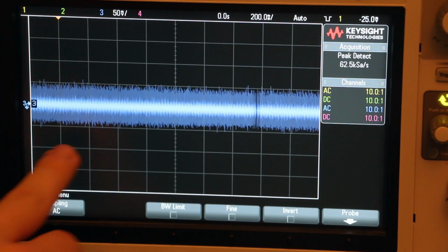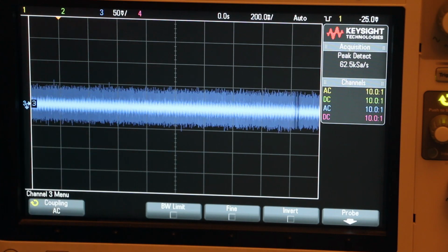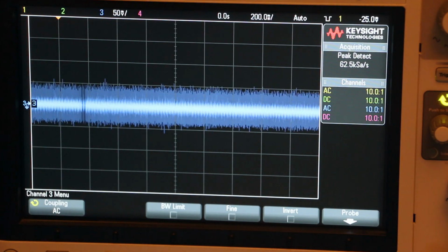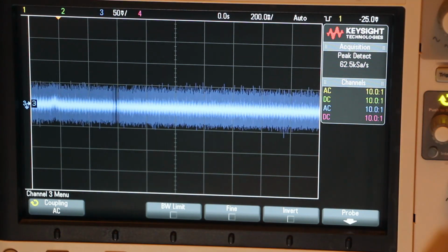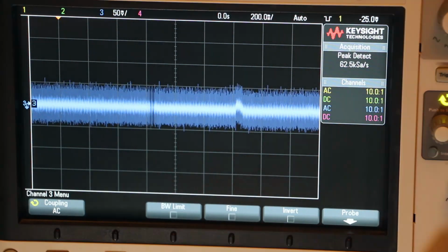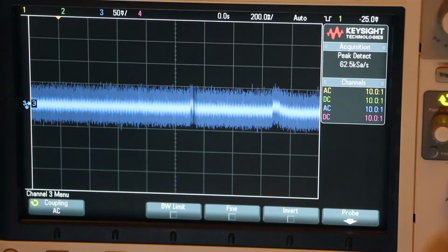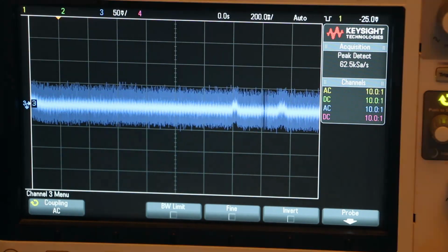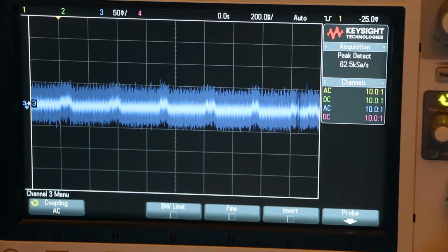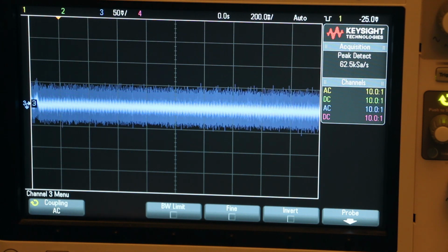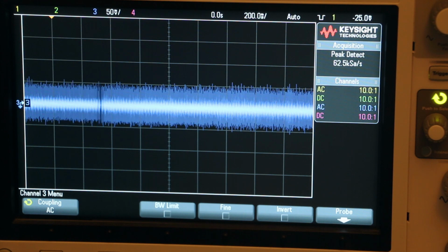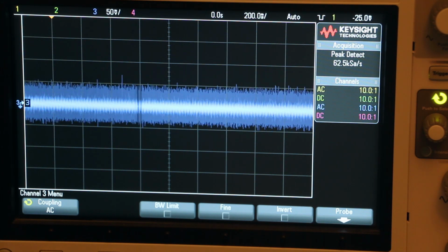As you can see, we're right down in the noise here. We've got 50 millivolts per division, and if I take that really bright LED torch I was showing you just now and bring it over and then far away, you can see that we get a bit of a spike. There you go. That is unfortunately nowhere near enough of a signal. If I was now to shine the LED chain at it, you can see what it looks like. Just nothing at all.